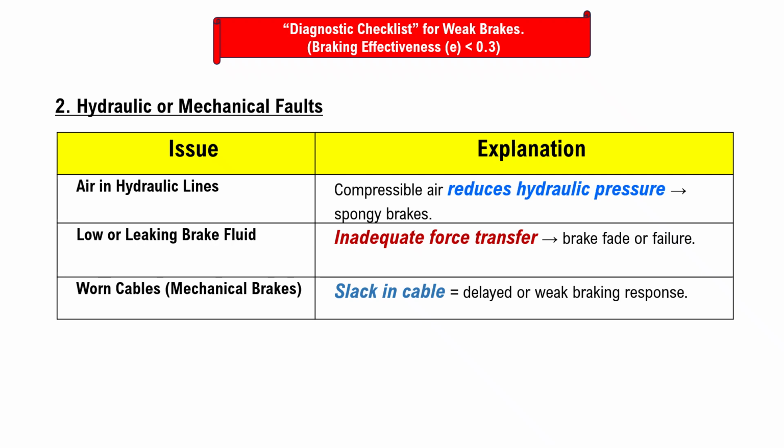The issues related to hydraulic or mechanical faults are: number one, air in hydraulic lines. Compressible air reduces hydraulic pressure, resulting in spongy brakes.